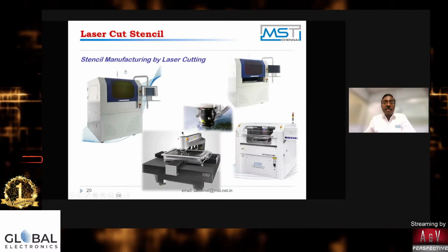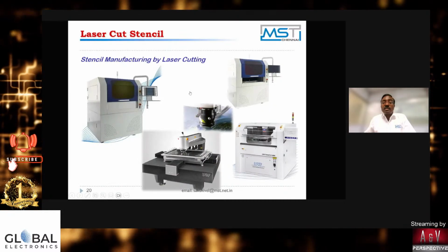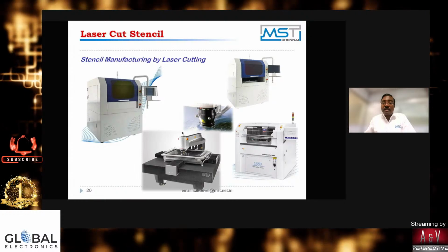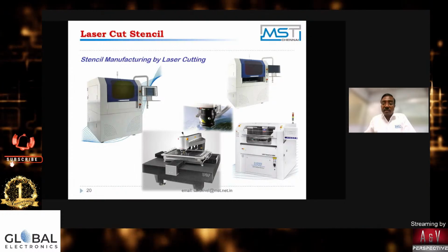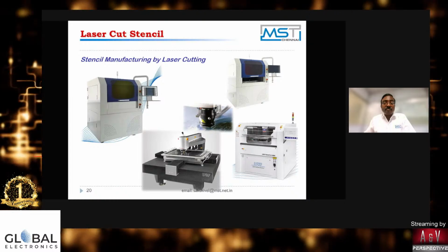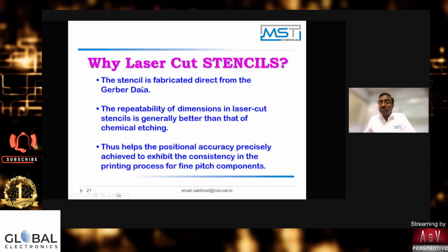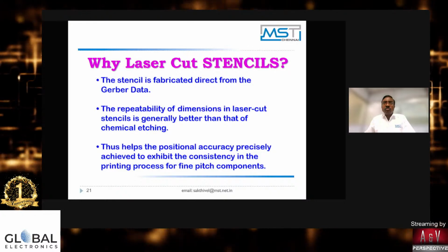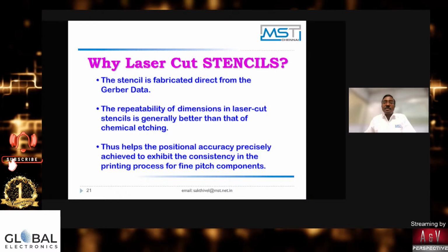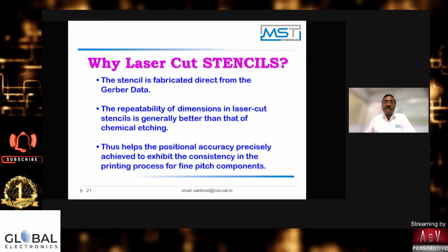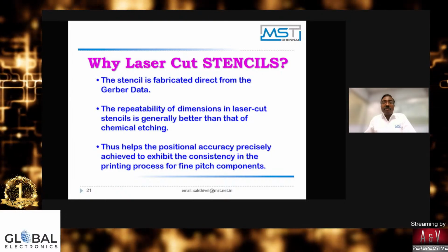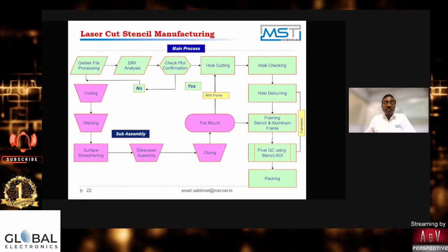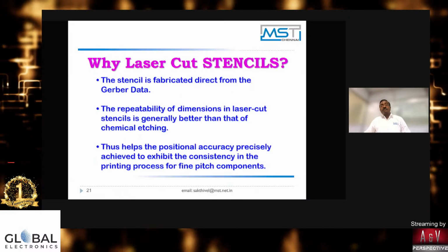But a laser cut stencil uses your Gerber file, your design data, as input to fabricate the one-to-one aperture openings. So the laser cut methodology is very efficient when compared with the chemical etching process? Far better, maybe even more than 200% better. And nowadays, digital design, which calls for HDI, etching definitely cannot perform. Correct, yeah, because of the very tight tolerance, right?